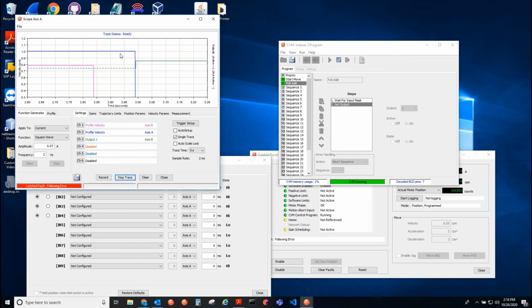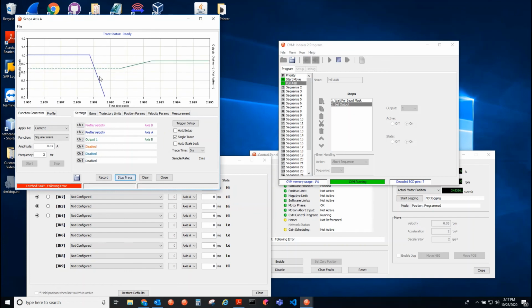If we zoom in here and look at this response time, that looks a lot better. Let's see. Looks to be about 2 milliseconds. So we shaved off a millisecond of response time by going with a hardware solution instead of implementing a software solution.